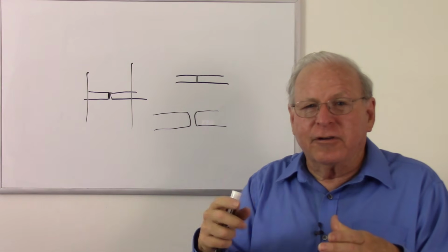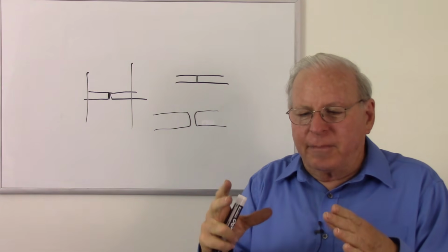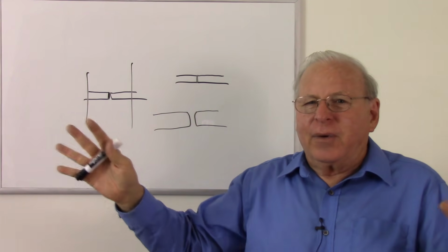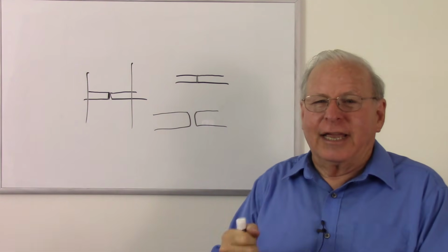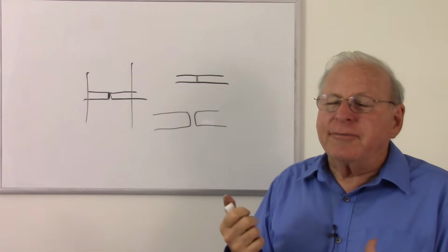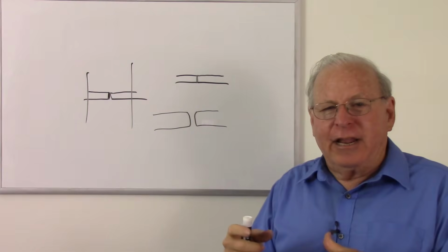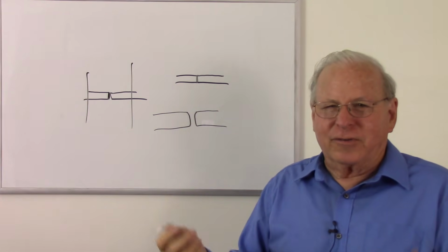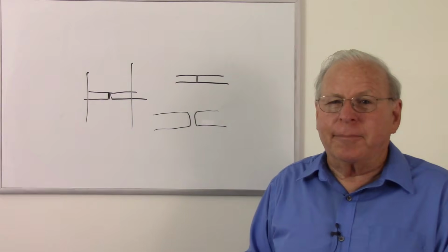But if you see curves, you know they don't match. But what he saw, he put it down, saw those interference patterns go zoop, and heard a click. They went into optical contact, and he could not get them apart. They were basically now one piece of glass. Since they were different types of glass, he was able to put them in an oven and heat them, and because of the differential expansion, he was able to get them apart. But he almost ended up with a piece of scrap because of this optical contact.